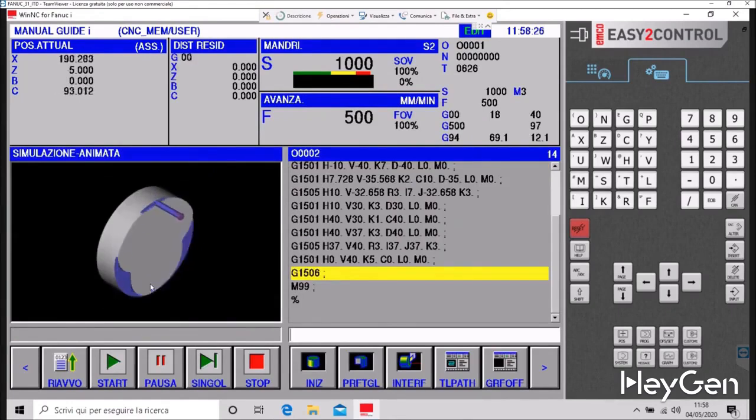The convenience of the subprogram is that I could have indeed increased the cutter radius a bit, so we wouldn't have to wait. See, I didn't link the roughing cutter's radius to the finishing cutter's radius at the point where we have the shank of the T where we will meet the cutter's radius. So, for actual machining, this could create a little problem.